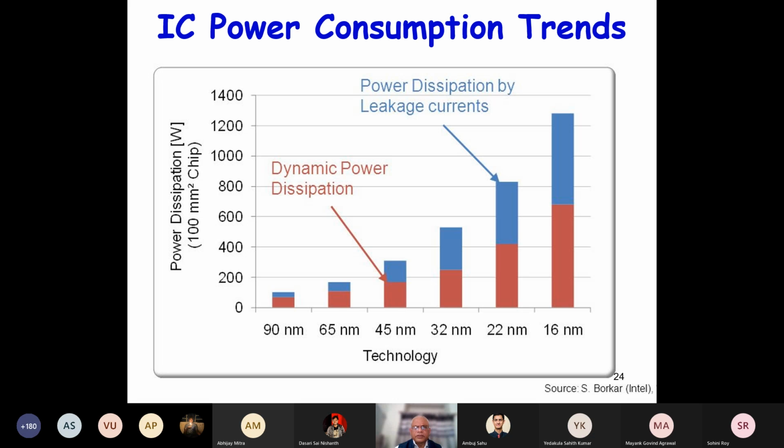Today we are at the end of the lecture. We'll stop here with this thought for you: what are these dynamic power and the leakage current? This has become a big problem, and it has hampered the performance improvement of computers. They cannot pack that many transistors, and also they cannot switch that fast. We actually switch off part of the processor as we go on. We'll see.